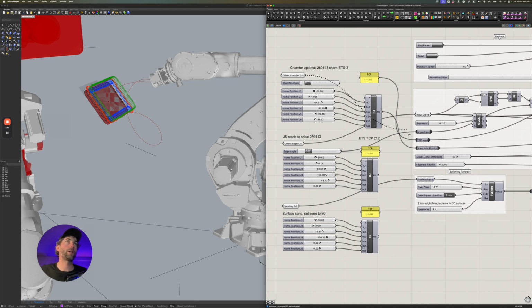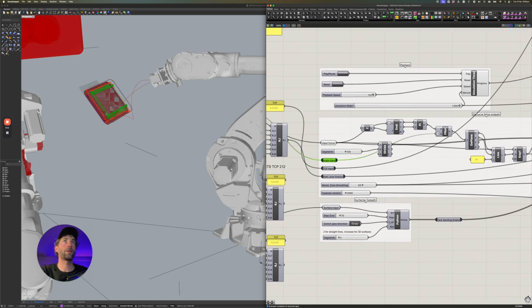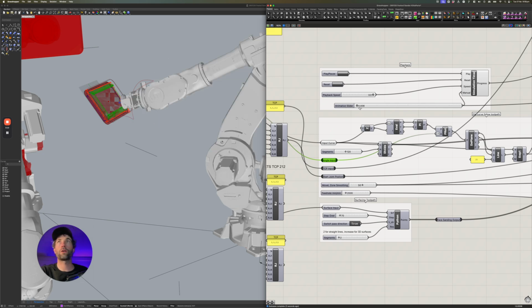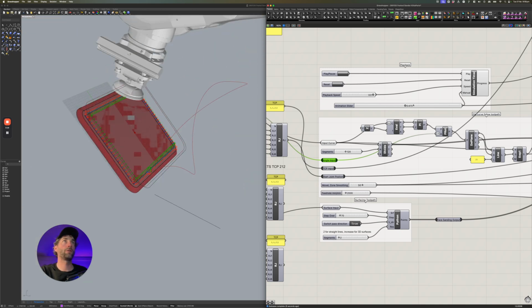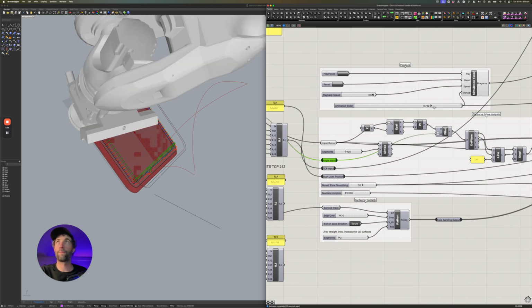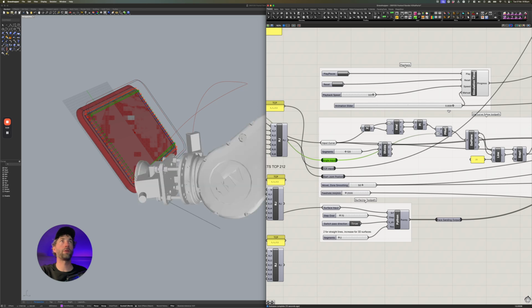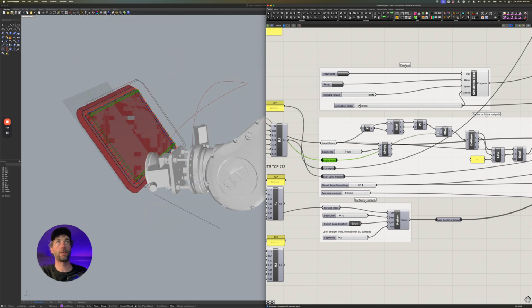And then it's just a matter of reconnecting curves. So if I want to program a chamfer or work on the chamfer, I bring that into my input curve, and then just work through and change start position, that's fine, TCP is fine, angle input. Bring from there. And then I can run my little animation slider and check what that's doing. Zoom in a bit for you. Bloop, bloop, bloop. All good. No joint clashes. Happy days.